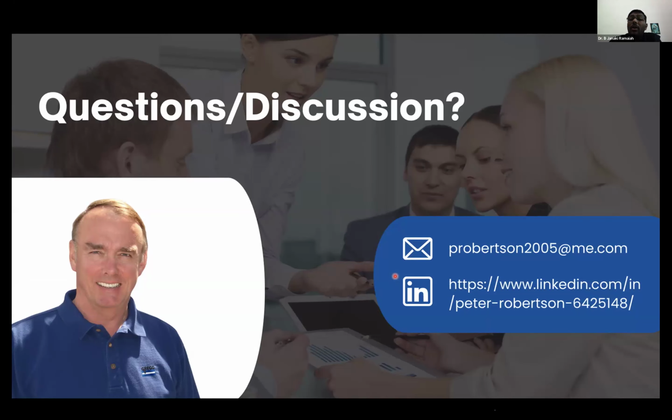The question is whether negative pore pressures are due to over-consolidated clay, dense sand, or unsaturated filters. Well, it can be any one of those. If you do dissipation tests and determine the equilibrium pore pressure, and it's hydrostatic, you extend it to get the groundwater. Even if it's not hydrostatic, there might be downward flow or artesian upward flow. If you do enough dissipation tests, you can extrapolate to where the piezometric surface is. So if you're below the water table, you know it's not due to partial saturation. Then the issue is simply whether it's an over-consolidated clay or a dense sand.